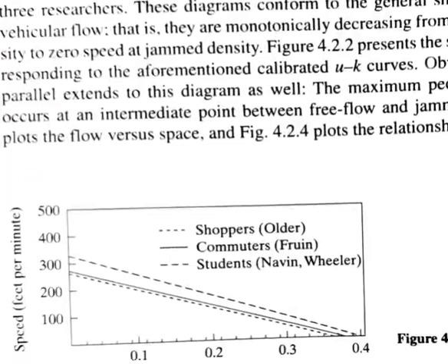Now what happens when the density is 0.1? The number of persons per square foot is 0.1. Then the speed is very high, nearly 280 to 320. I'll tell you once again. Along the x-axis is the density, and along the y-axis it is speed. So when the density is near 0, the speed is 280 to 320.